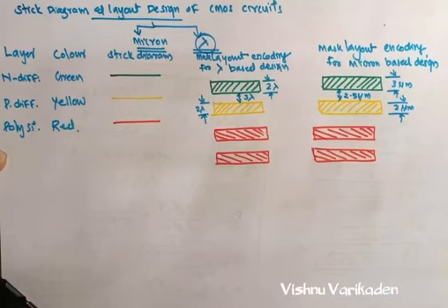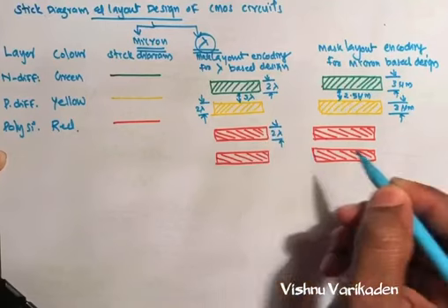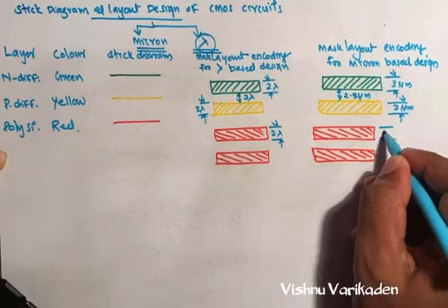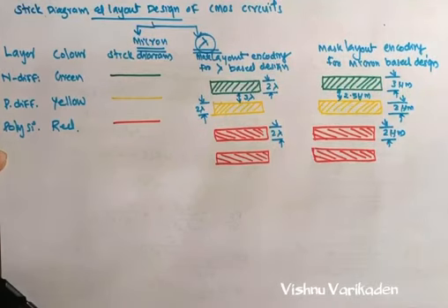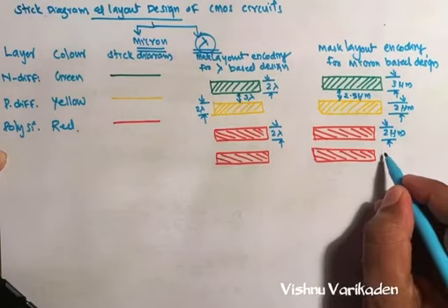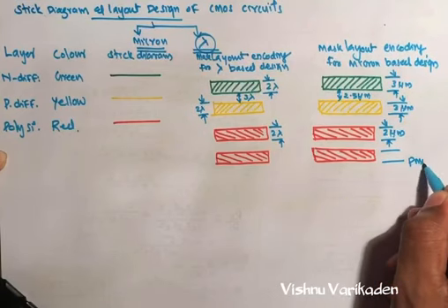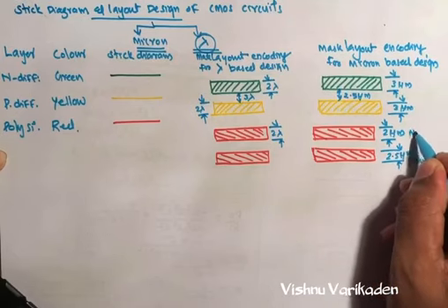The size of the polysilicon is 2 lambda in the lambda case. In micron based it is also 2 micrometer, and for CMOS it is 2.5 micrometer. This is for NMOS.